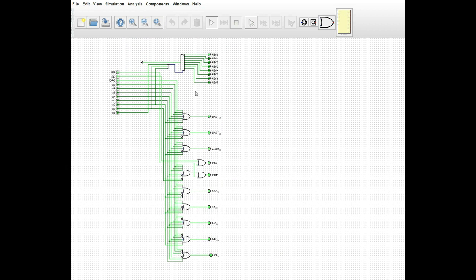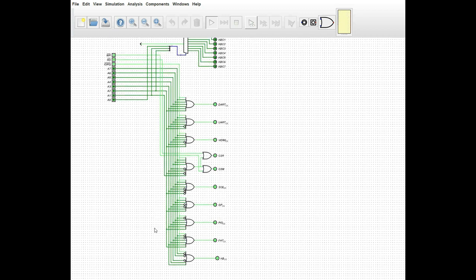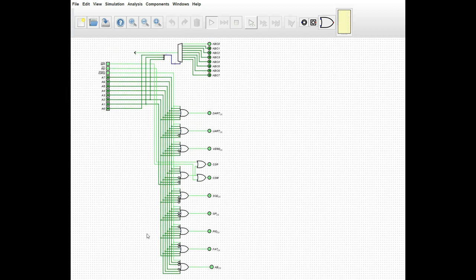And we've got, like I said, quite a bit of chip selects here. That's more I/O than most do-it-yourself computers actually have, or at least a lot of them anyways. There's some of them that probably have more, but they're not on a CPLD for the most part. So we've got this all internal. This isn't going to use up a lot of logic. This is only going to use up a very small amount of gates. You're probably looking at a couple macro cells, because OR gates, they're cheap whenever it comes to CPLDs.